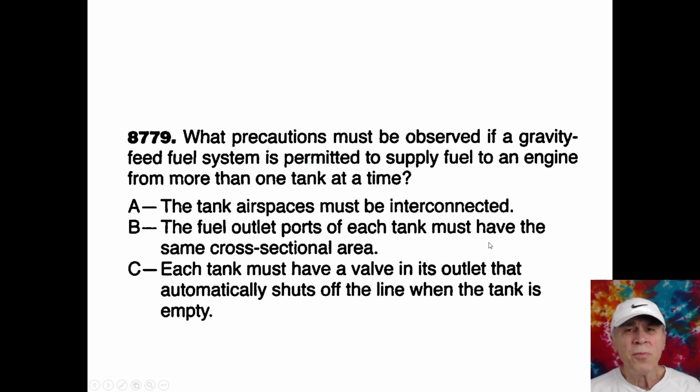What precautions must be observed if a gravity feed fuel system is permitted to supply fuel to an engine from more than one tank at a time? What precaution if you're going to have a single engine receive fuel from both tanks at the same time? I'll make sure that pressure is going to be equalized. So how would you do that? A, the tank airspaces must be interconnected. Well, that's probably good enough right there.